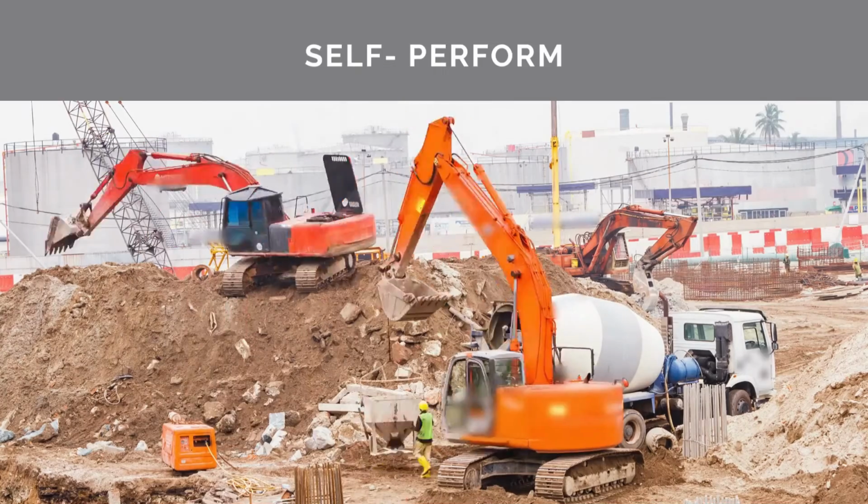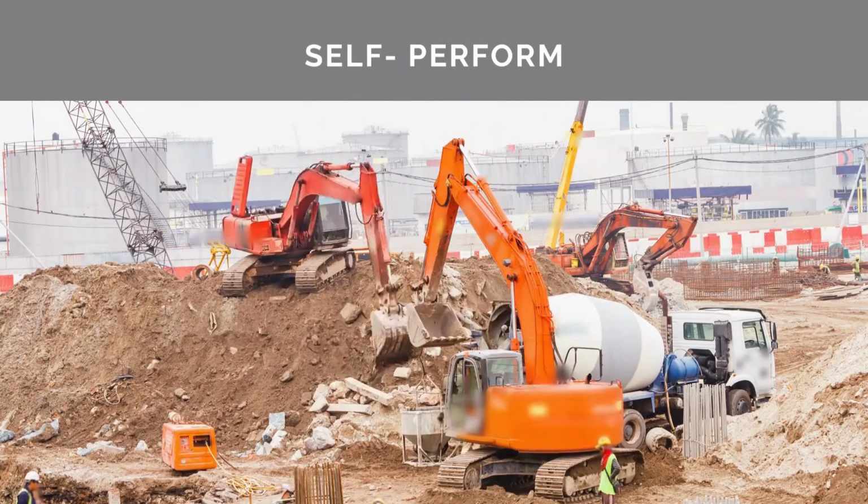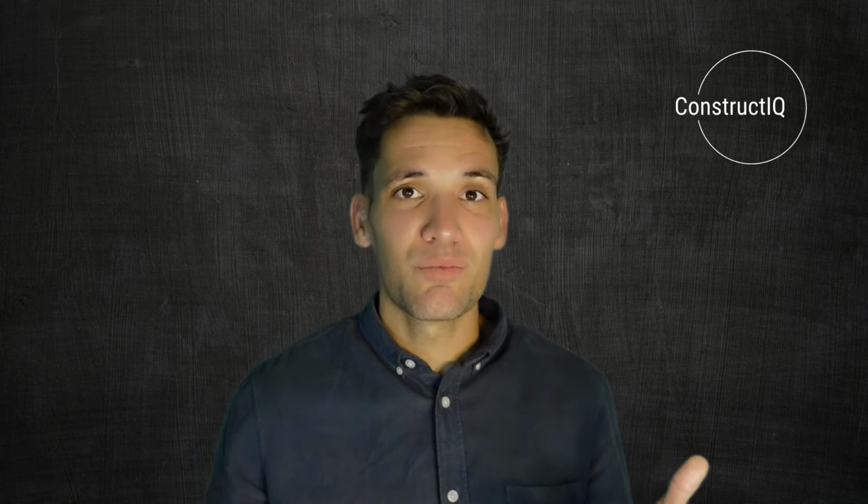Now, bottom-up estimates we use when we're self-performing the works. This is where we're using our own labor, plant, and machineries to complete the tasks. And for these activities, we should do a full bottom-up estimate and then cross-check it with a top-down or parametric estimate. The other way we can do works is we can subcontract them.